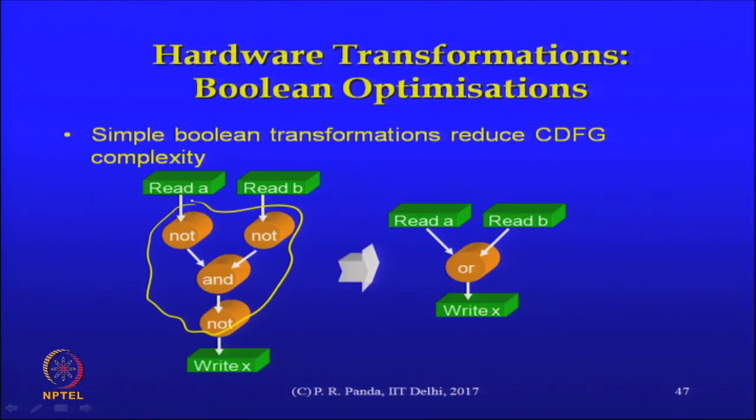The idea is that these are very simple operations, even though they may be operating on large bit width data. Since these are bitwise operations, the time taken will be small, and there may not be a need to explicitly schedule these kinds of operations, considering that you also have other operations being scheduled that are going to dominate the clock period anyway.